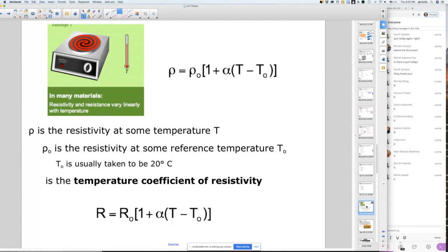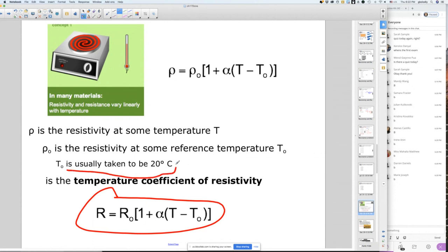This thing we call resistivity of a wire depends on what the wire is made of, but it also is affected by temperature, it turns out. When a wire gets real hot, its resistivity changes. So this is the formula that it follows to change. And that means the resistance changes by the temperature. So usually the temperature we're talking about, if we ignore temperature, is room temperature, 20 degrees Celsius. But if it's a very high temperature or very low temperature, this resistivity will change.